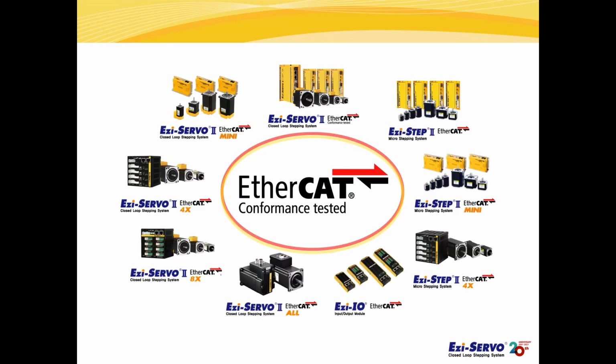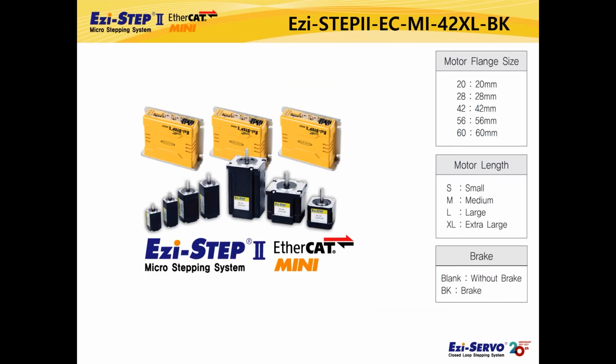The next product to be introduced is the Ezi-STEPII EtherCAT MINI, a compact mini drive product of an EtherCAT-based open-loop micro-stepping system. First of all, I will explain the combination model name of Ezi-STEPII EtherCAT MINI product. In the example model name, EC means the product using the EtherCAT network, MI means mini drive. 42 means 42 mm motor flange size, and XL means motor length. BK means that a brake is attached on the motor.